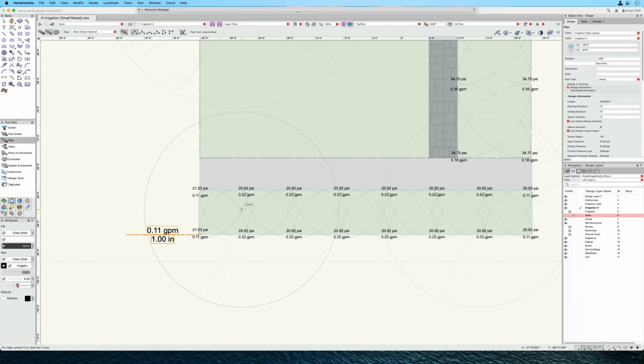So here I need to work around this. Let's go ahead and I can individually connect to each one of these. And you'll notice that as I connect, it's totaling up how many gallons per minute I have. So you could individually connect these any way that you want. And I'll go ahead from the other end. You'll notice I'm not adding this because they're not connected to that line. So we want to make sure that everything is connected appropriately.